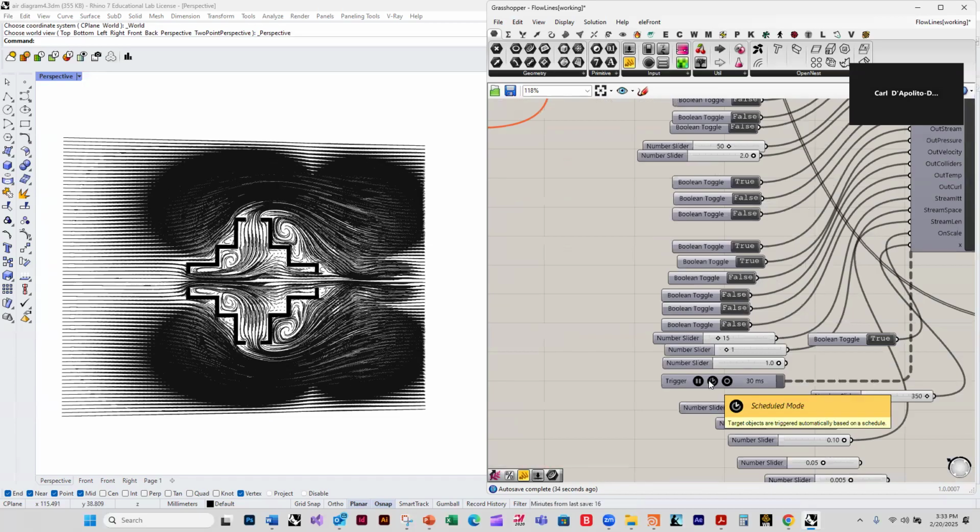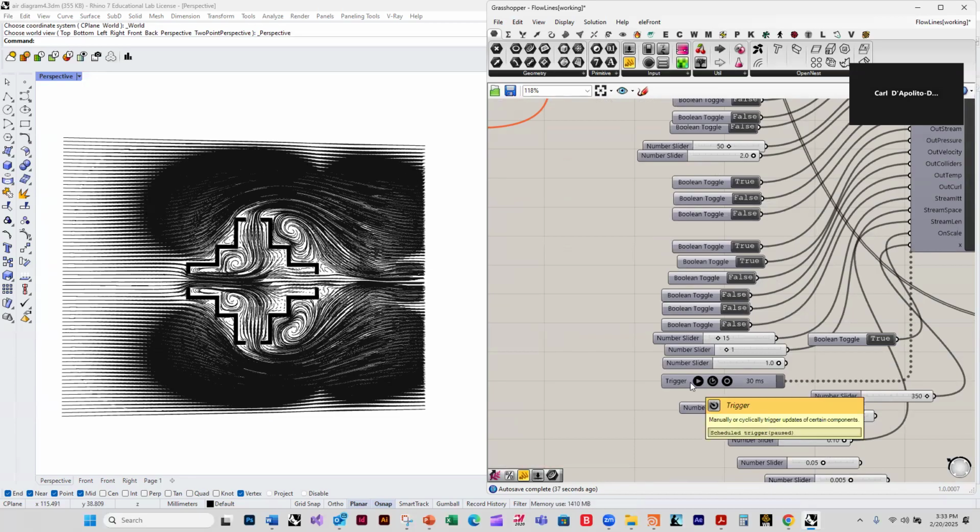Can you explain what the data dam does again? Yeah. So the reason for this, and if I were to package this up in Visual Studio, I'd be able to get rid of this. But because I've left it open, I can't think of another way to do it. What's happening is that every time step, all the inputs get reloaded into the Grasshopper thing, even though we're not using them. It's loading thousands of values every second. And so if I just dam the data from going through, the simulation will run faster.